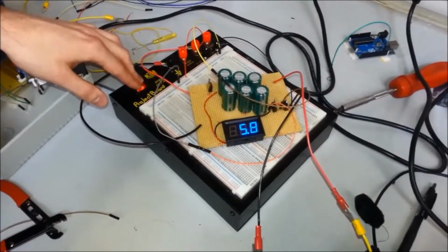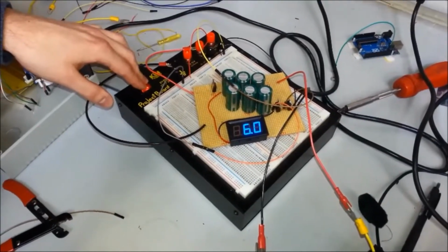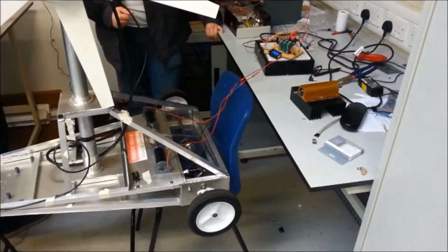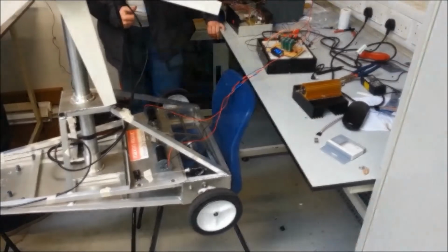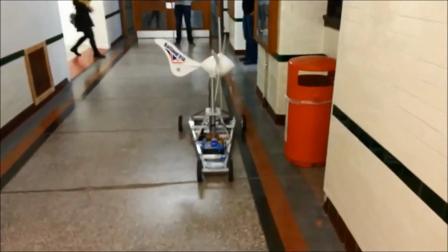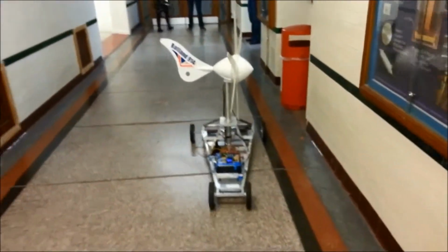Energy storage was implemented in the third-scale model using supercapacitors. The Aeolus race permits a 30-metre push start before the timed section of the race begins. The supercapacitors have been installed in such a manner that they can be charged by both the turbine and the motors, which have been configured to act as generators during this period. This ensures a significant amount of energy has been captured which can be utilised throughout the duration of the race.